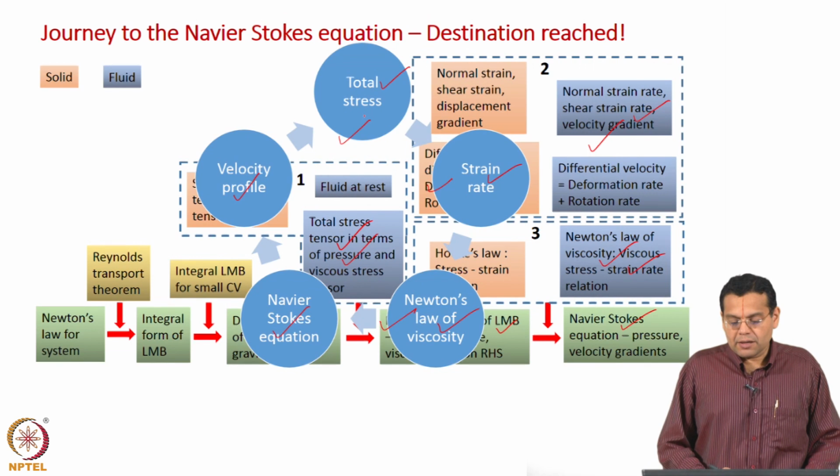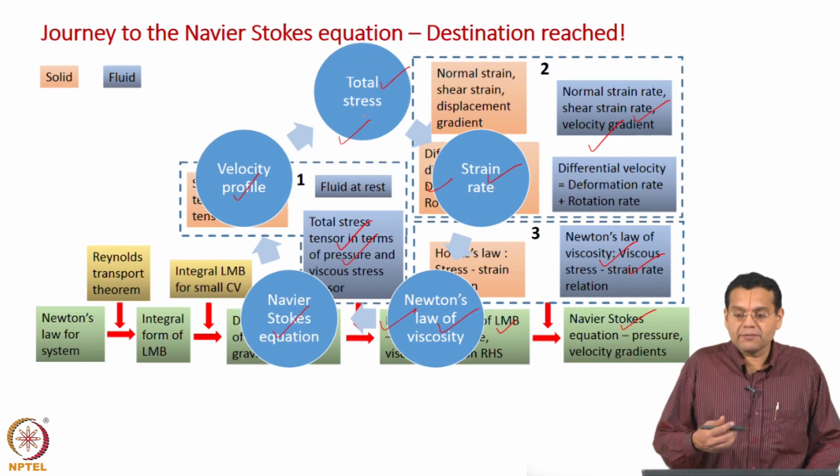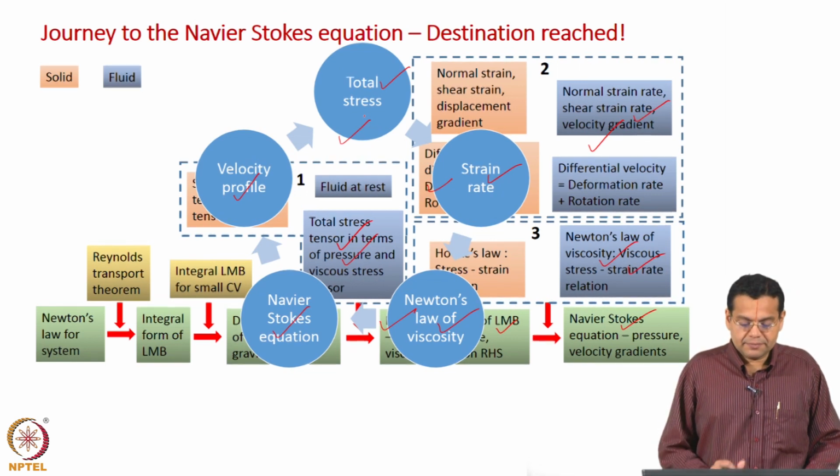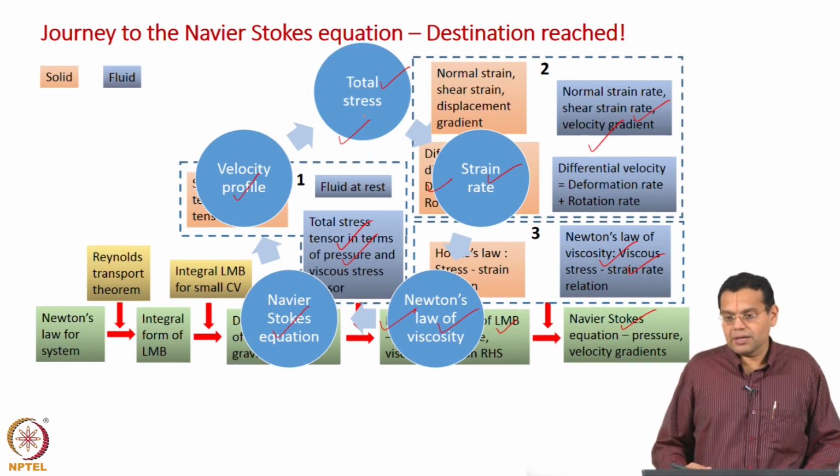Okay. Now, once we have derived the velocity profile, we can evaluate all the variables which we have introduced. For example, dou v_x by dou y was a derivative. Now, we can evaluate dou v_x by dou y, okay. And then physically meaningful variables like the strain rate, and then the viscous stress tensor, and then you can also show the stress element, etc. Okay. So, this is one way this helps us to understand the path we have followed and why we followed that.